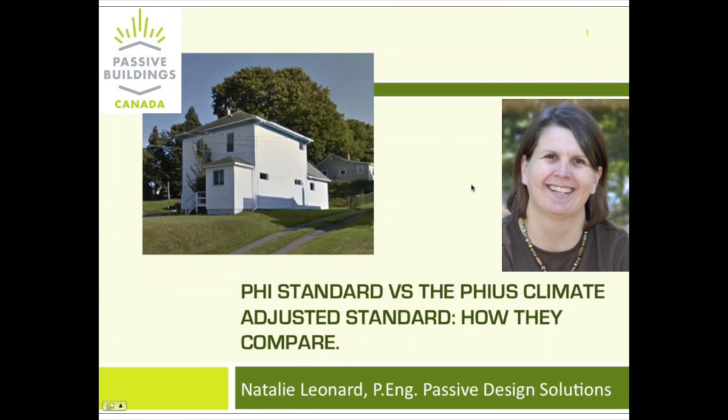This building has been occupied since April. So this is the first winter, and they have monitoring data in the building, but I don't have any of that data yet. But the hot water heat pump was placed in the basement next to the storage, with extra venting into it. So I don't expect it'll be affecting comfort based on some of our other decisions, but it's definitely discounted in the energy performance in PHPP with that calculator.